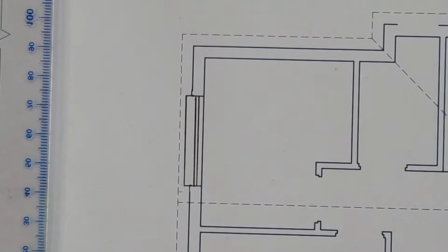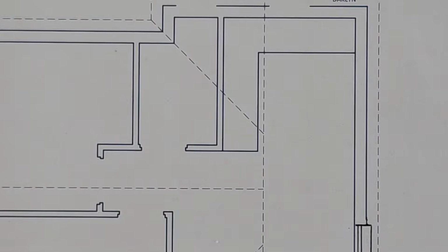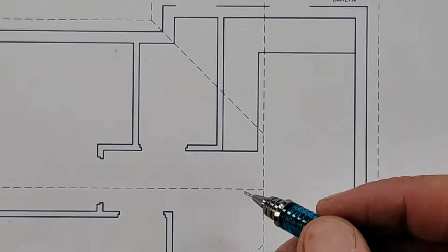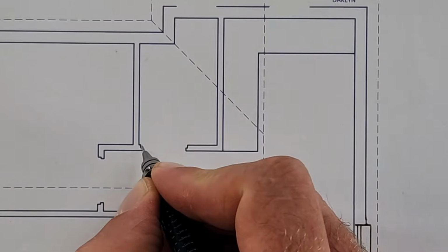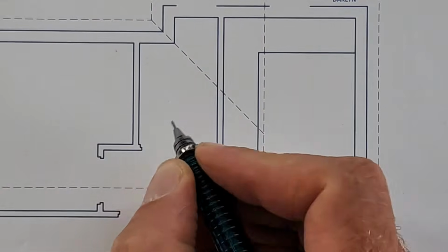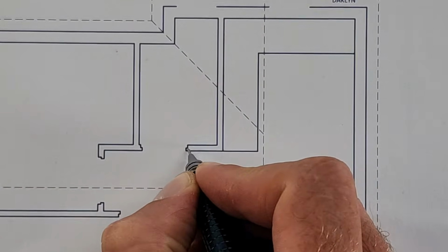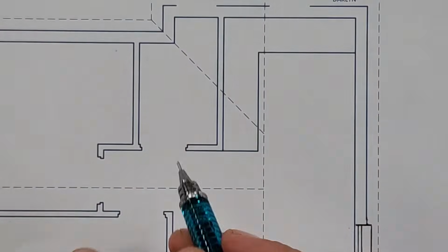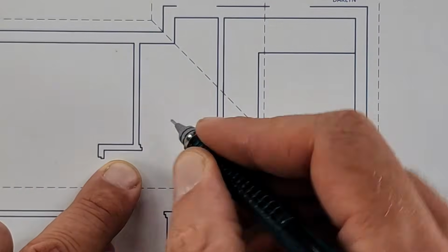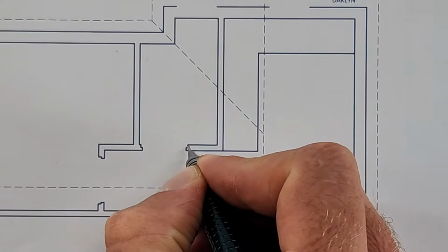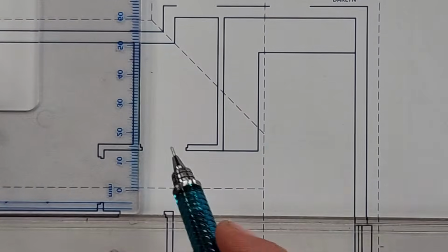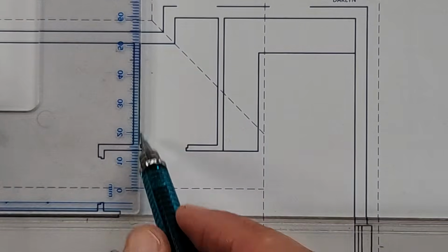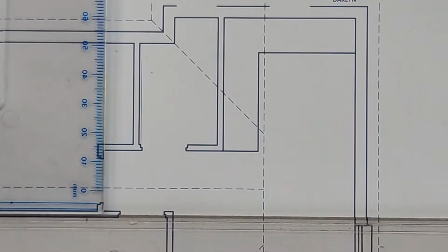Right, let's look at the door because there's another hack here. All right, I'm going to keep in the zoom level because I want you to be able to see clearly. Okay, so this is your door frame, that's the recess, that door closes in it, okay? This bathroom, they don't tell you direction, but if we can, we're going to want to open the door onto the wall. So what I do is I start on that corner with a construction line, okay? Yes or no? All right.